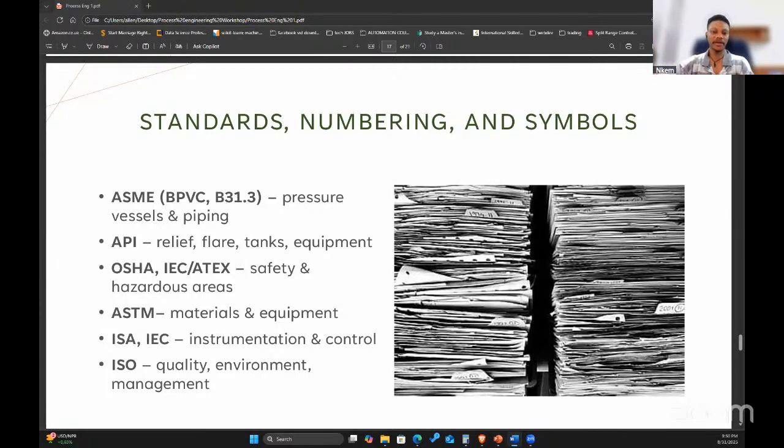Whenever pressure gets to this point, you should relieve at 4 bar so that it never gets to 5 bar. So there's an allowance for it. So this API guides the laws and the rules for the design pressure of your relief valves, your flare systems, and storage tanks, and all whatnot. Okay, so that's for API.